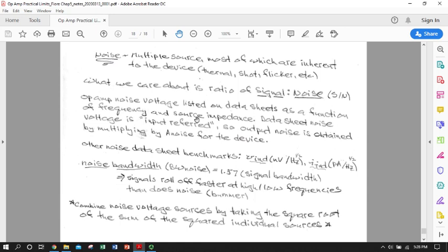When you talk about common mode rejection ratio and getting rid of the common mode signal, which is frequently noise, or defining the power supply rejection ratio, all of that is starting to touch on the concept of noise. And these are signals that you don't want. These are voltage signals or current signals that can be amplified, that obscure your ability to detect the signal that you cared about. Like foreign object and debris, noise is any kind of signal that gets in the way of you detecting the one you wanted. It's everything other than the signal of interest.